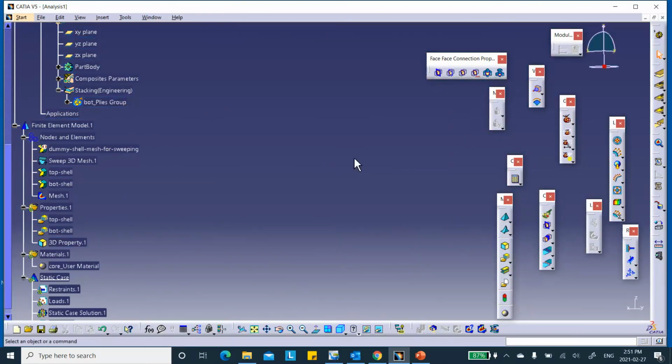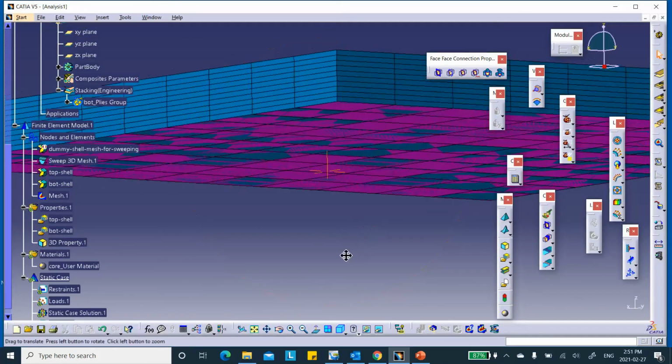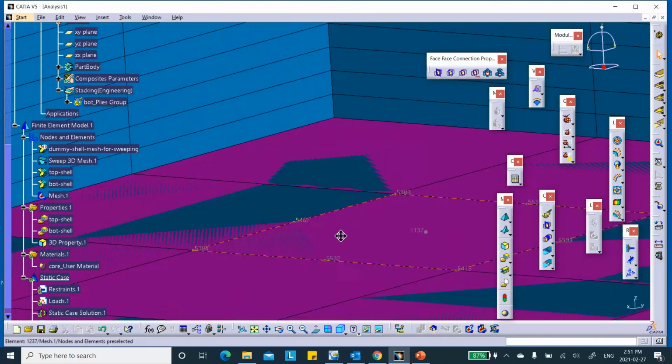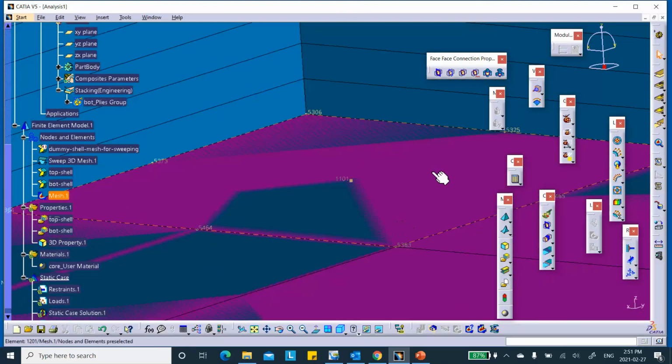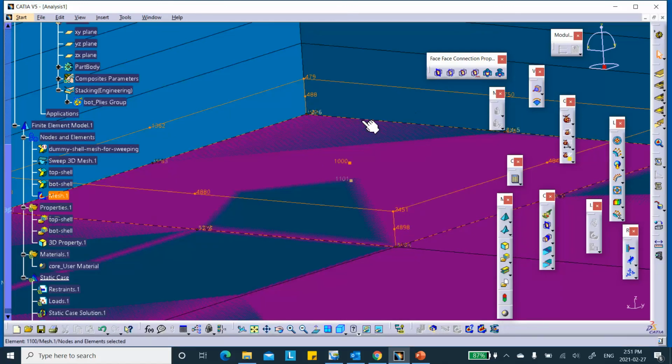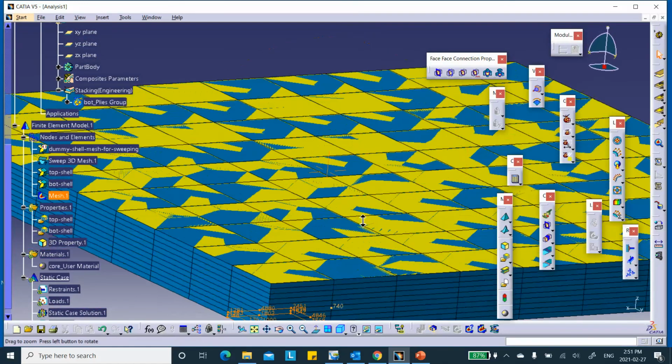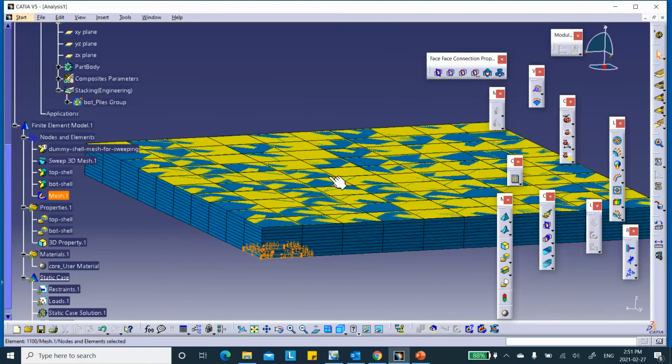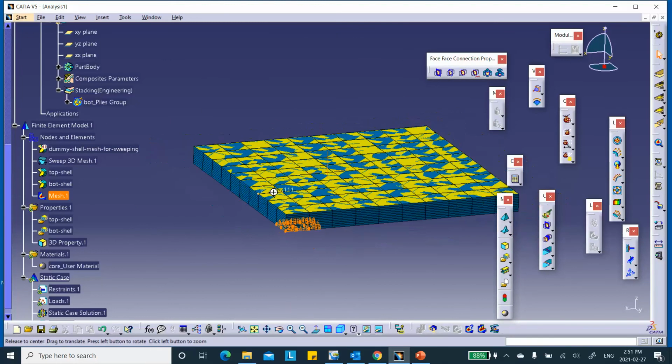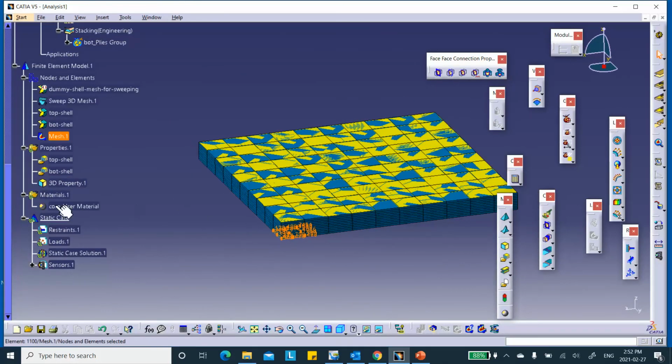And the same thing is true down here. Let me rotate this a little bit. Look at this element that's closest to you. If you select the shell, it says node 5306. But if you select the solid, it's a different node number, 345. These are not the same nodes, but they have to move together, because if these are perfectly glued together, these are kind of the same thing. What I have to do is create an analysis connection between three parts. Whenever you're doing assemblies, you need to create analysis connections.